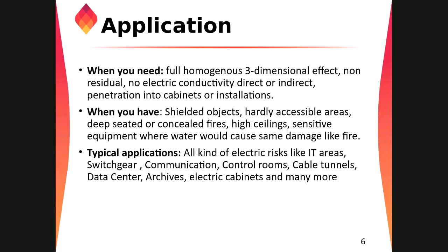So what are the applications for the clean agent suppression system? The meaning of clean agent is that once the agent discharges, it will not leave anything behind. When you need a clean agent system, you need a full homogeneous three-dimensional effect. It is a complete flooding system.